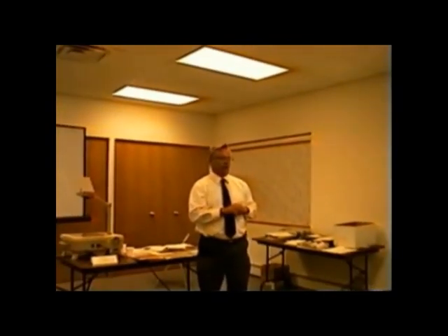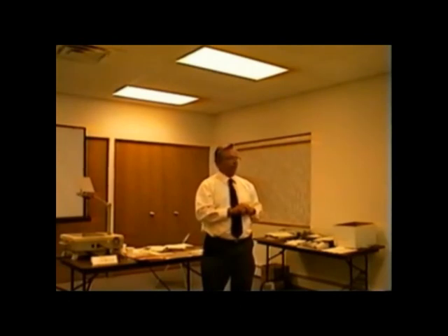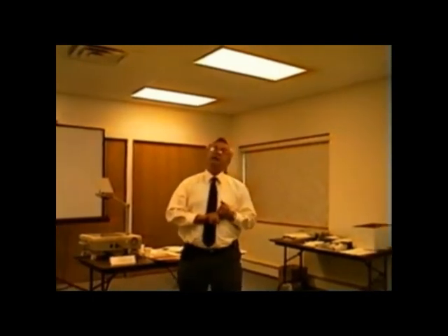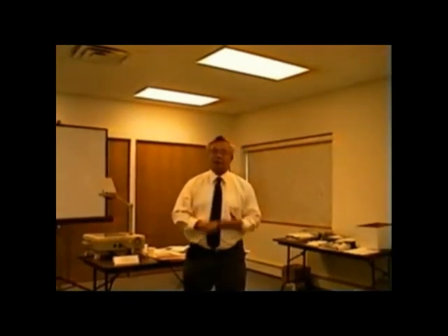So if we ask a contractor who's at the job, what's the voltage to the furnace? What's the technician apt to tell us? It's how much? 115 volts. Absolutely, 115 volts or 120 volts. And at that point, ladies and gentlemen, we're going to tell the technician, would you please go back and check the voltage, because we know that he hasn't checked it.